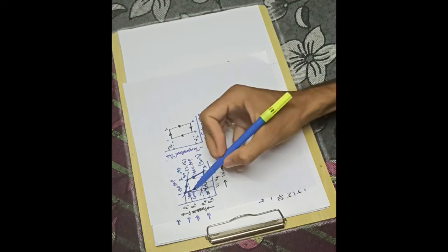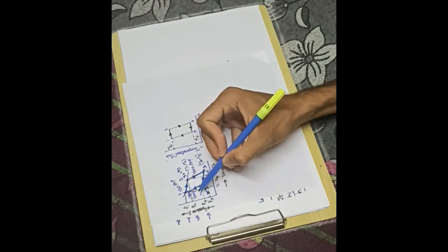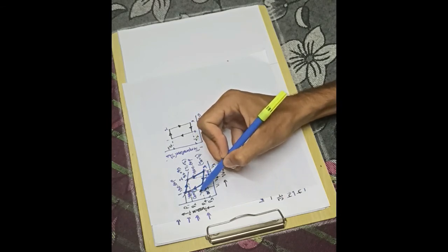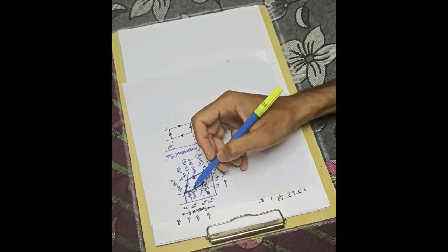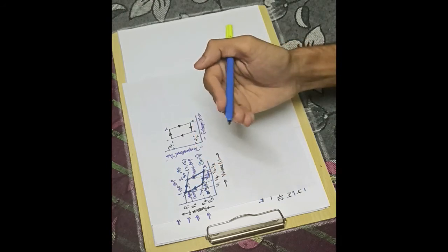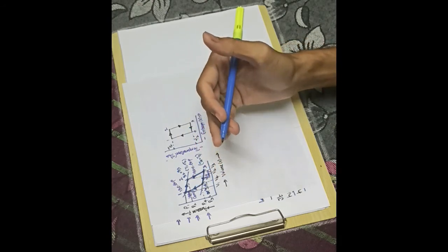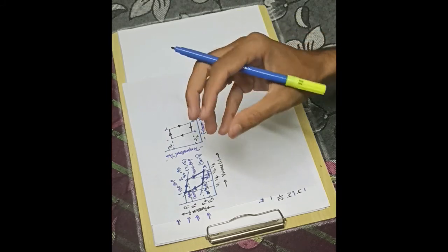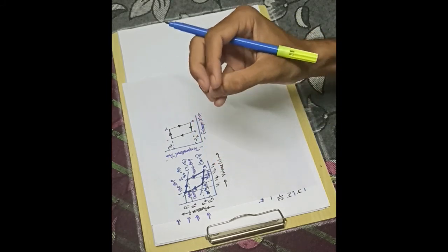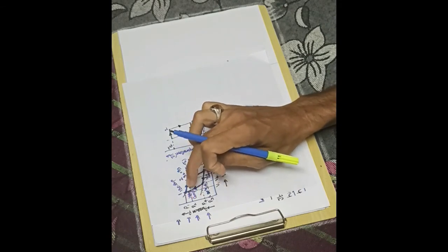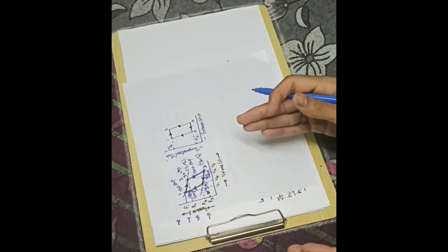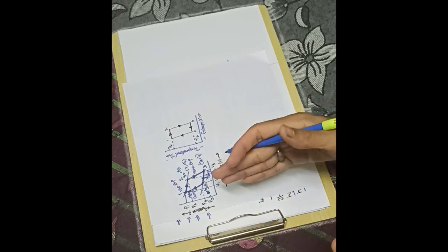Next, coming to the fourth process, isentropic compression: no heat is absorbed, nor is heat rejected. What happens is an increase in internal energy, which is done not by the air but on the air during adiabatic compression. That is what happens in isentropic compression. So this is about the PV diagram.